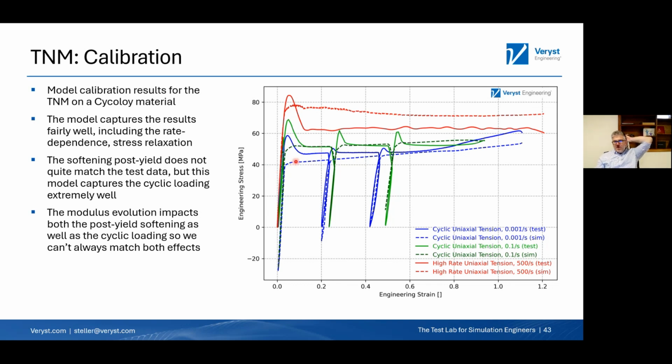Here we're at a little bit low of a yield stress. So depending on your application, you might definitely want to tweak this. But for going over 6 or 7 decades, this is a good start here. And you can see that it's capturing that unloading response a lot better. And up here at 50% strain, it really captures that unloading well, not as good at the really small strains. We see a lot of that stiff unloading that we saw with the metal plasticity, but this is orders of magnitude better than what we see there.